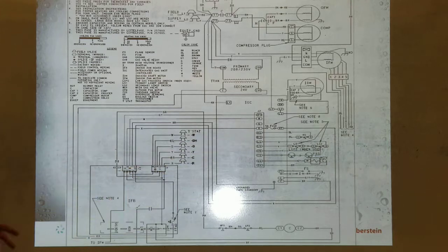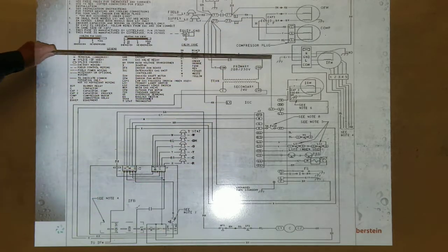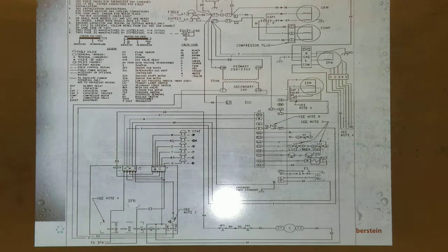So if you have a low voltage problem, then you're gonna go from there. If you've got a high voltage problem, it'll be up on the top here. It's not necessarily gonna be up on top and bottom. It's gonna be separated by the transformer itself. You just gotta figure out where the transformer is: high voltage on top, low voltage on the bottom.